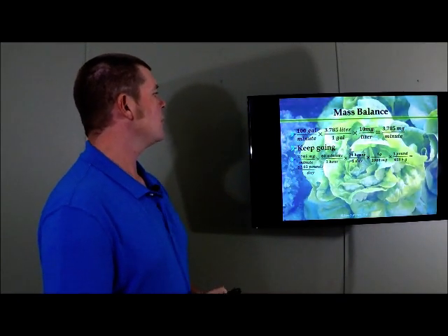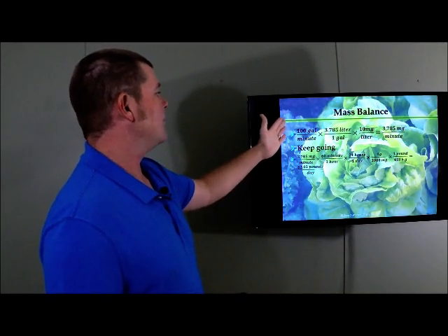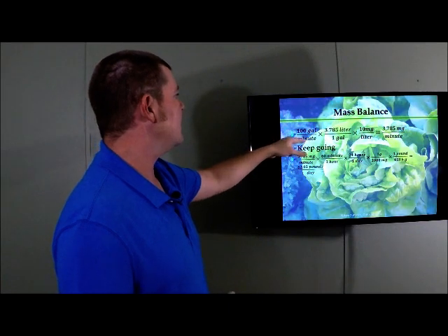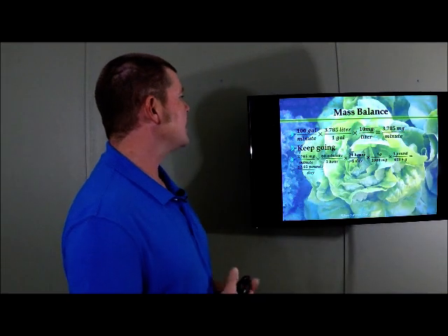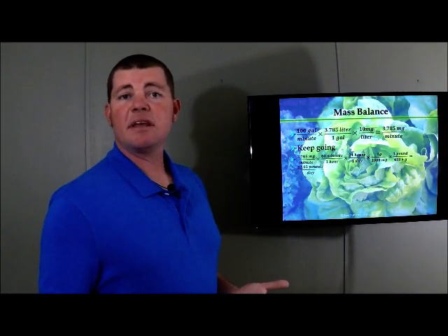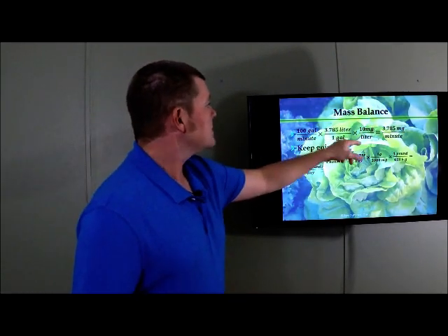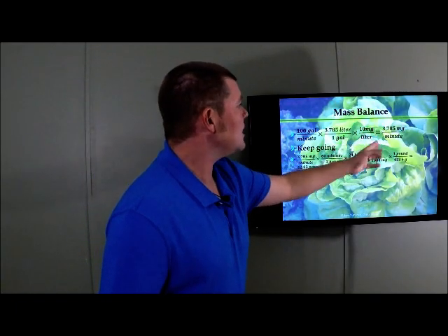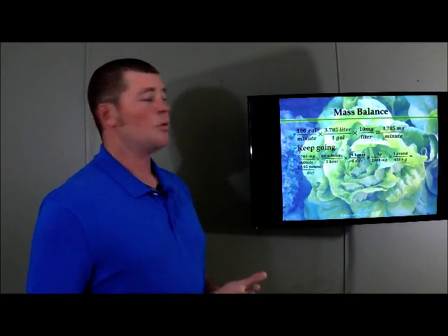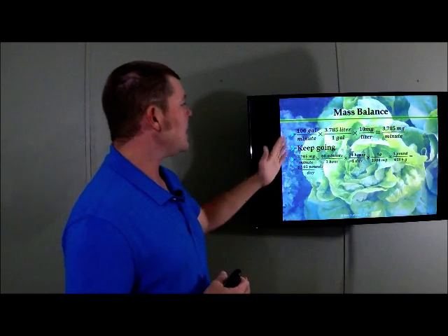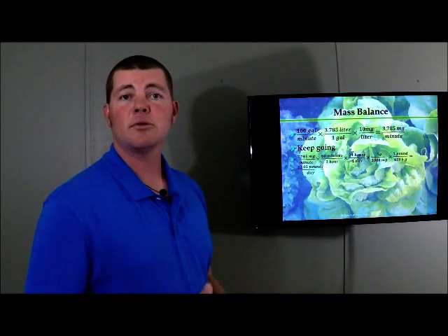So from that original formula, we're going to go ahead and do a little bit of unit conversions here. We've still got 100 gallons per minute, but now we're going to add in 3.785 liters per 1 gallon. Because there's 3.785 liters in 1 gallon, and we eventually want the gallons to cancel out. So times 10 milligrams per liter equals 3,785 milligrams per minute. So now we're getting somewhere. We're extrapolating these out, and we're getting to a point where we're actually going to be able to cancel out some of these factors and get a real-world number that tells us something.